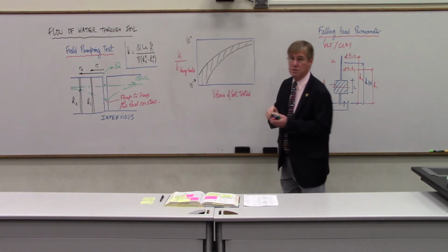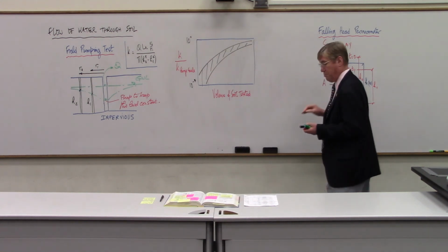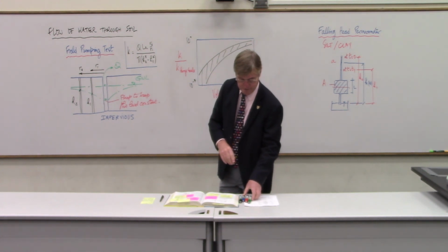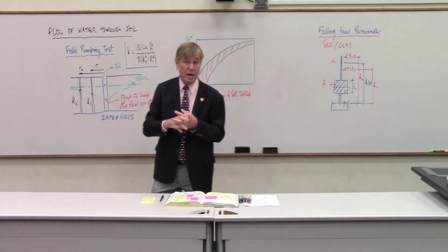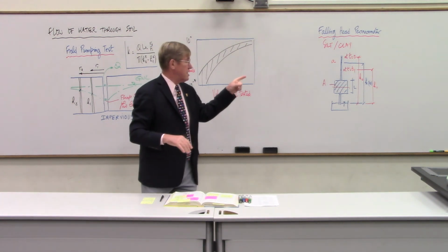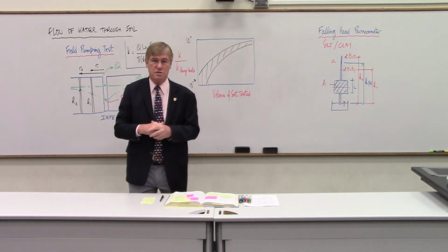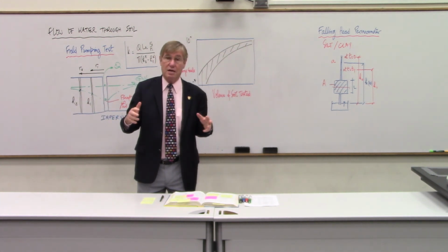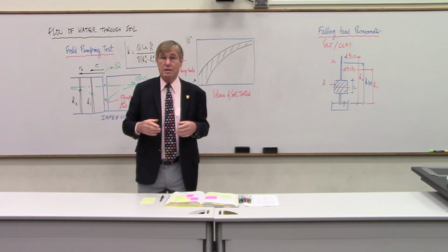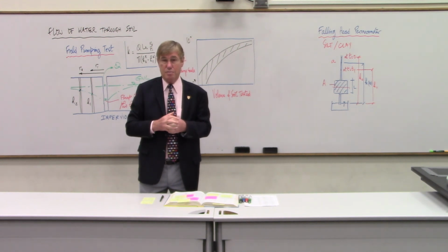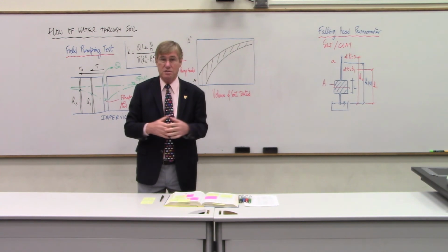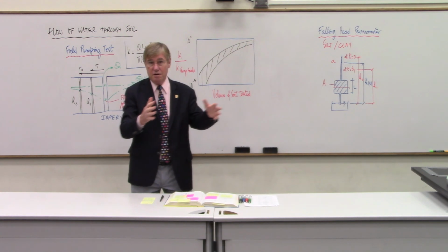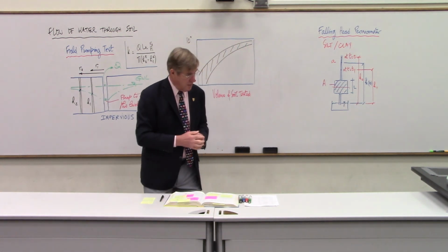So be very careful with this, that when you measure things, for example, and I'll stop here, I'm over time. If you test a landfill liner, and you do some tests, and you say, oh my goodness, no water will ever go through this liner. But you build it at the large scale, and there may be some cracks. And you find out that when you run those field tests, you have a much higher permeability that doesn't pass the specification. So be careful and keep in mind that field scale permeability is a lot higher than lab scale permeability. All right, thank you. We will see you next time.